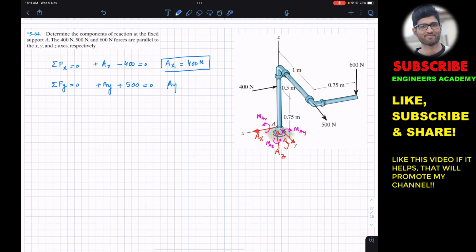From this we get that AY is equal to minus 500 Newtons. The minus sign tells us that the assumed direction of AY is not accurate. AY is actually acting towards A, so the initial assumed direction needs to be reversed. So AY magnitude is 500 Newtons and it is acting towards point A, in the negative Y direction.